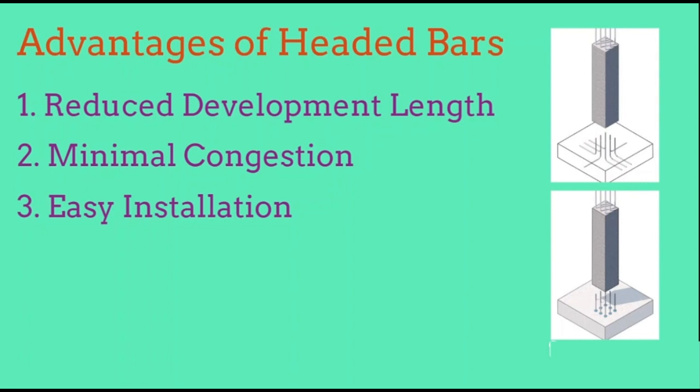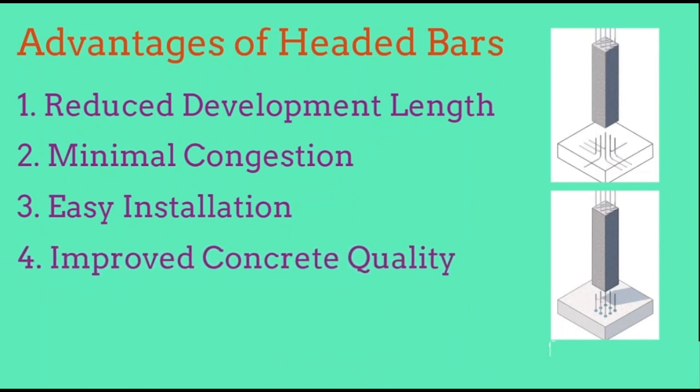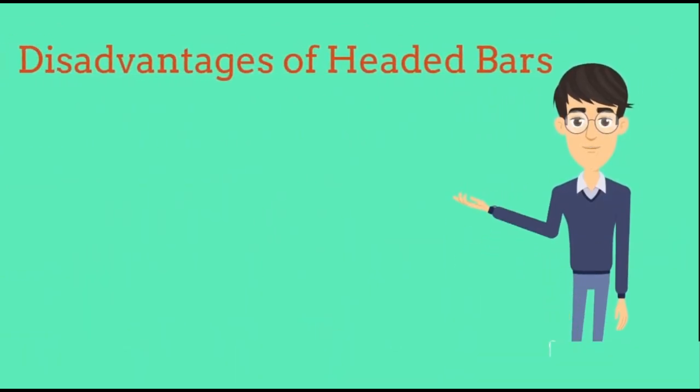4. Improved concrete quality. Heavily reinforced areas can benefit from the use of headed bars, which help reduce congestion. This improved arrangement allows for better consolidation of concrete, resulting in higher concrete quality overall. Now, let's address some of the potential drawbacks associated with headed bars.